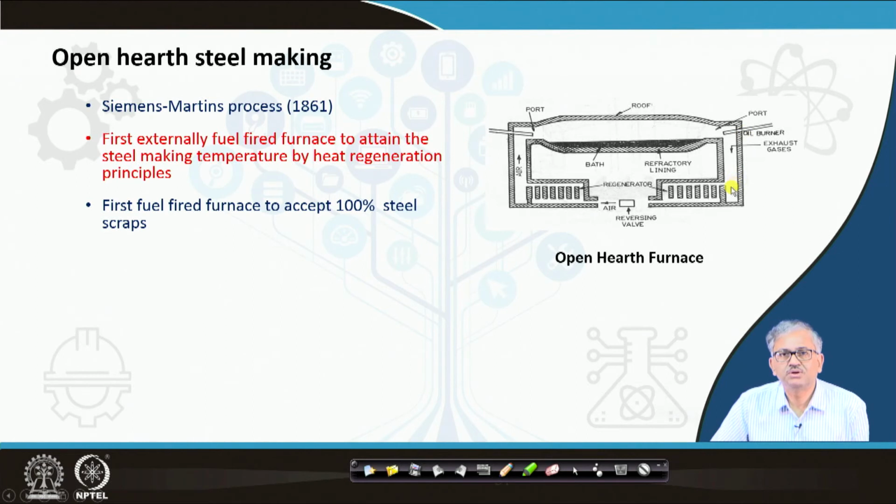When the exit gas comes out, there are checker brickworks. Checker brickworks, as I say, are nothing but brickworks with a lot of surface area, such that your heat exchange becomes very effective, and the brick can retain the heat. So the exit gas exchanges heat with the brick, and the brick gets heated up and stores the heat, and the gas then goes to the stack.